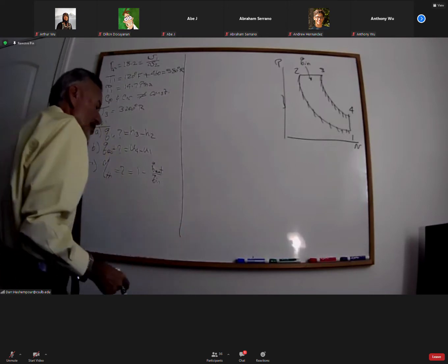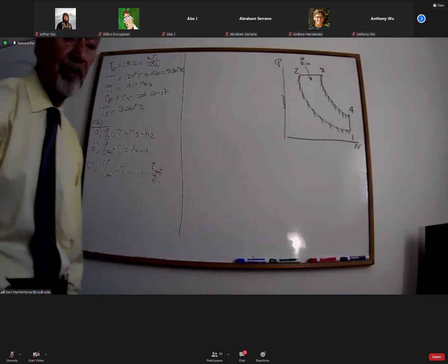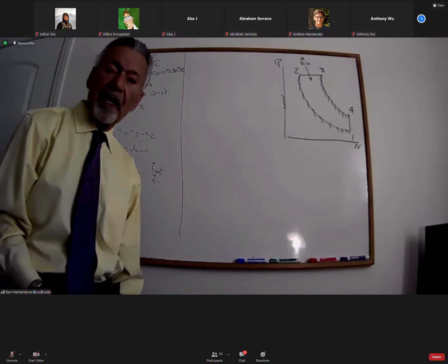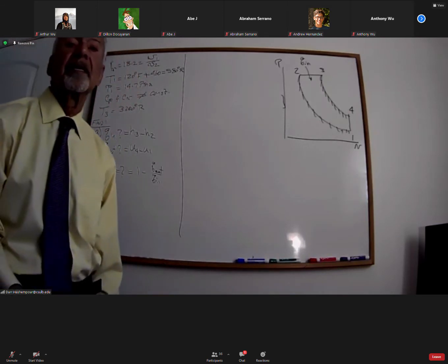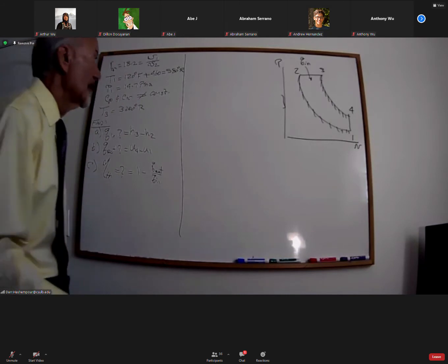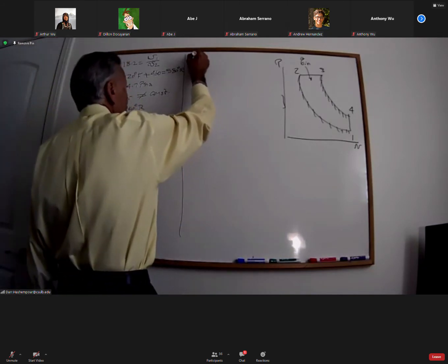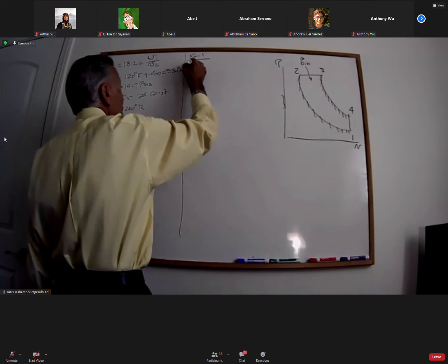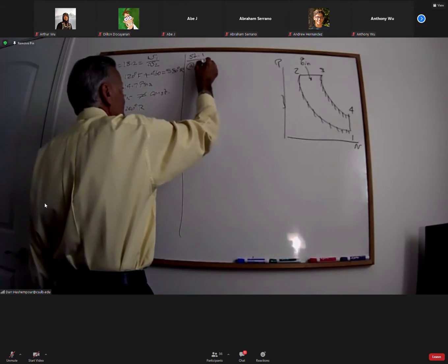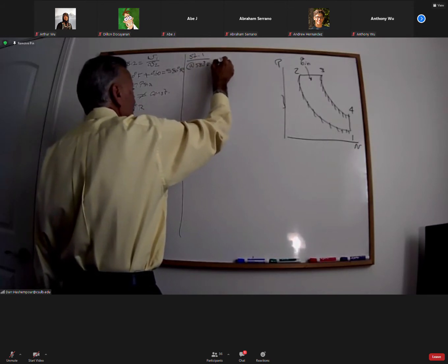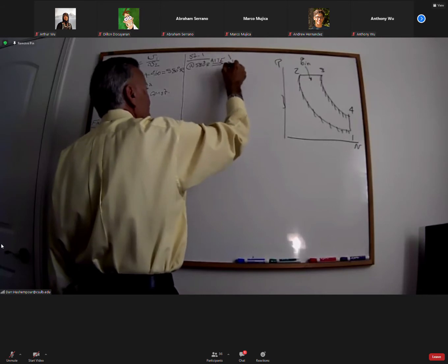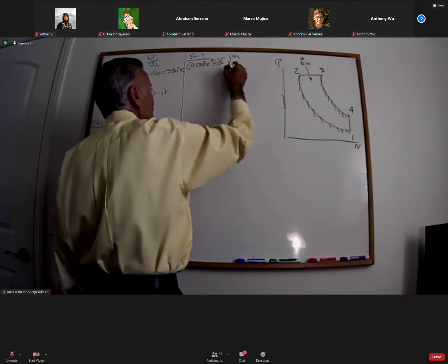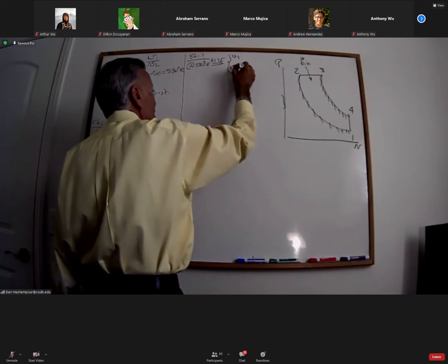For those of you that are supposed to have your textbook with you, I want you to go to table A17E, or English unit. At state 1, at 580 degrees Rankine, I go to table A17E and I find the values of U1 and VR1.